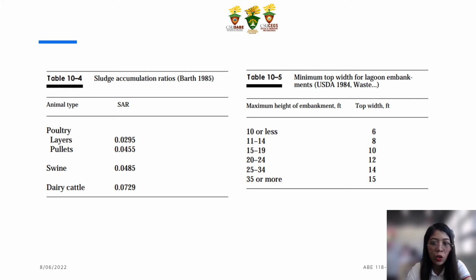The minimum acceptable depth of an anaerobic lagoon is 6 feet. But in colder areas or colder climates, at least 10 feet is recommended to assure proper operation and odor control. The design height of the embankment of the lagoon may be increased by the amount needed to ensure that the design elevation is maintained after settlement.